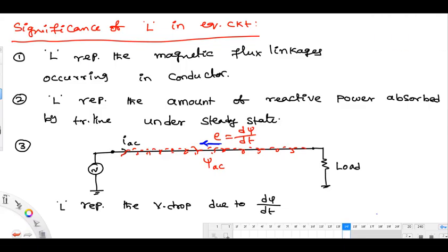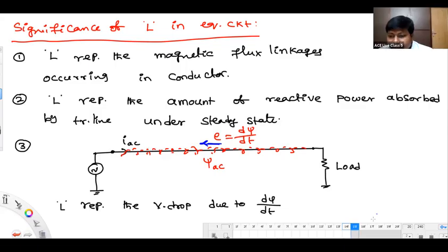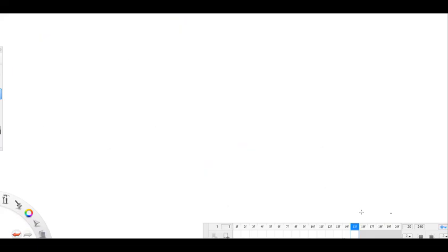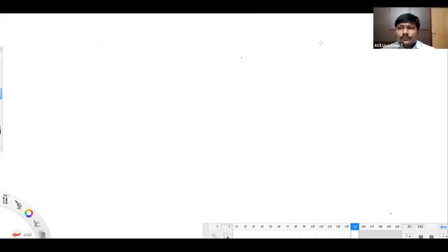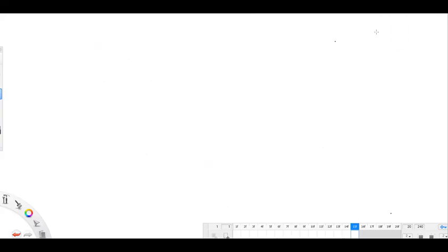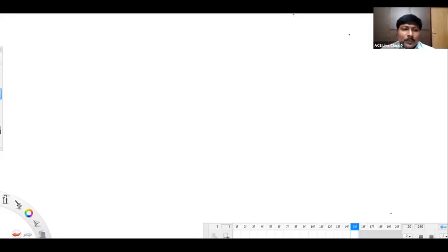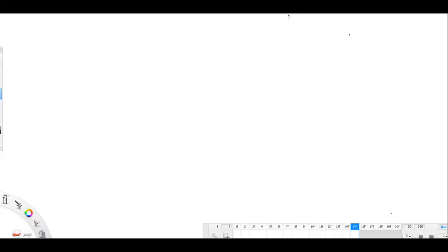Sir. Yes, sir. Can you hear me, sir? Tell me. Yes, sir. My doubt is regarding ACSR conductors. Sir, in skin effect, the current is concentrated on the surface only. And for removing that, we are using the stranded conductors. Whereas in the stranded conductors, we have again made the same kind of arrangement that the current is concentrated only on the surface of conductors. But you see, your point is that the skin effect is not reduced. Is it your point? Yes, sir. I am seeing no difference.